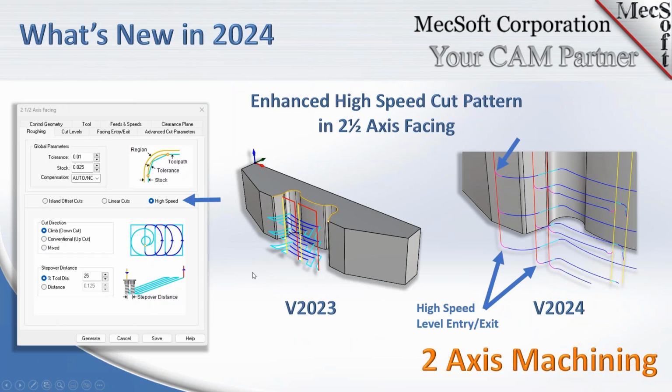Now also, as Joe mentioned, we enhanced the high-speed machining in 2.5 axis spacing. So not only do you have the high-speed tool paths at the cut level, but you also now have the high-speed entries at the entry and exit level. You can see these arc motions right here where the arrows are pointing. So it adds a high-speed entry at each cut level and a high-speed exit, as well as the high-speed path itself.